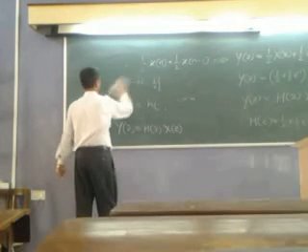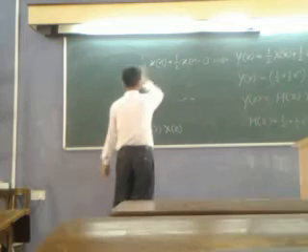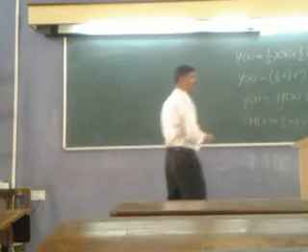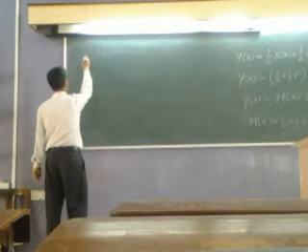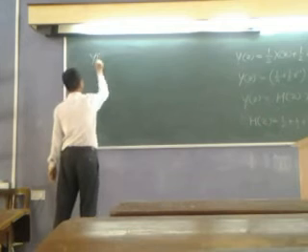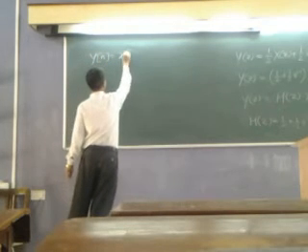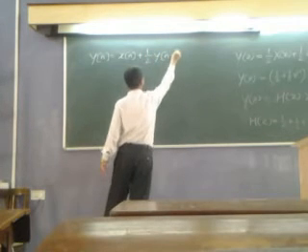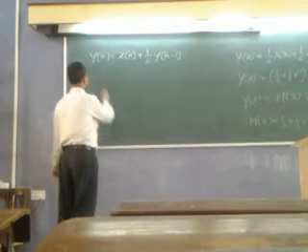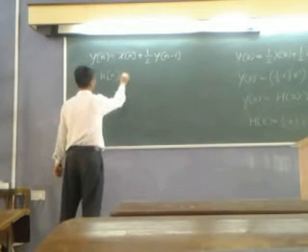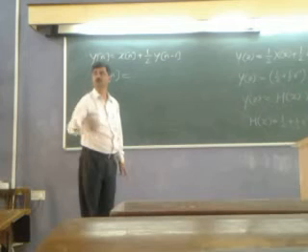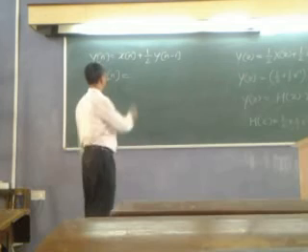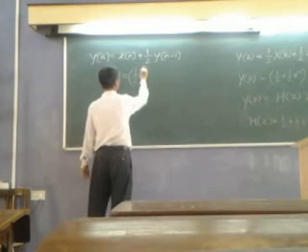We have got the system equation as yn is equal to xn plus half yn minus 1. And what is hn there? Hn is half raised to n un, right? If h0 is 1, h1 is half, h2 is 1/4. So half raised to n un.